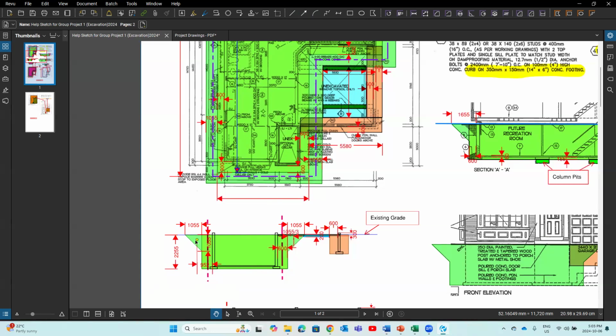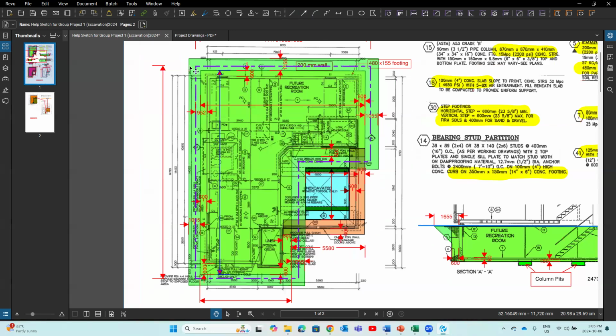After I get the cross-sectional area of this triangle, which is the slope around, right? I multiply by the length. The length, we cannot see from the section drawing, but we should figure out the center line length on the foundation plan, right? When we talk about the length of the wall, we look at the center line. The center line length of that wall is the length of that wall.